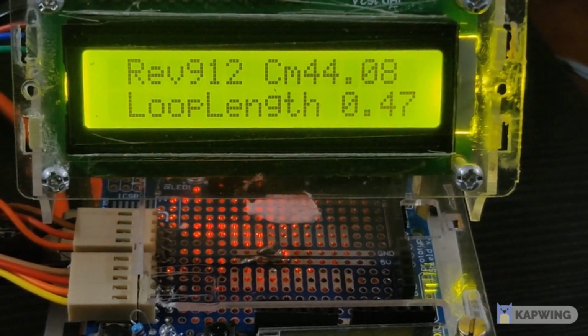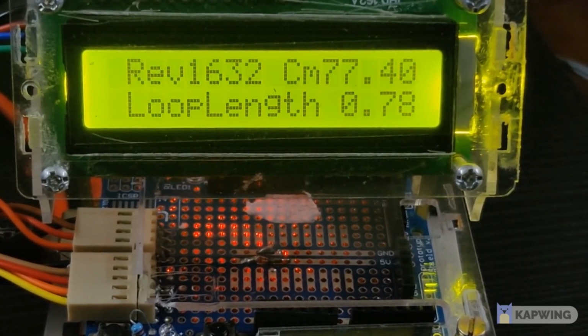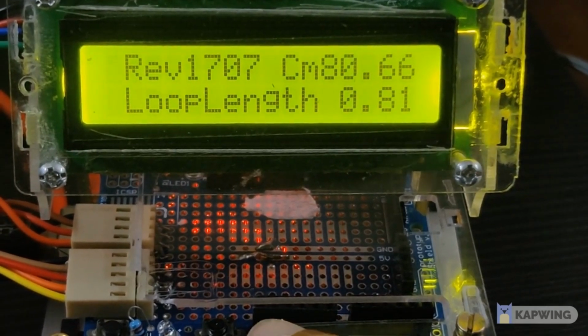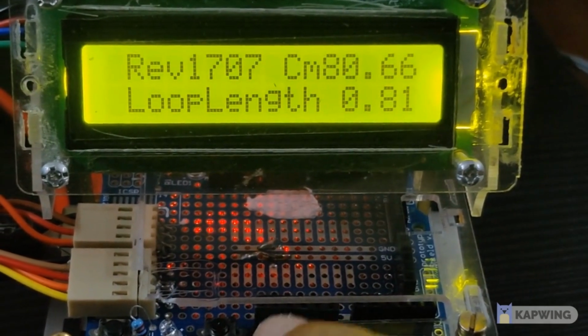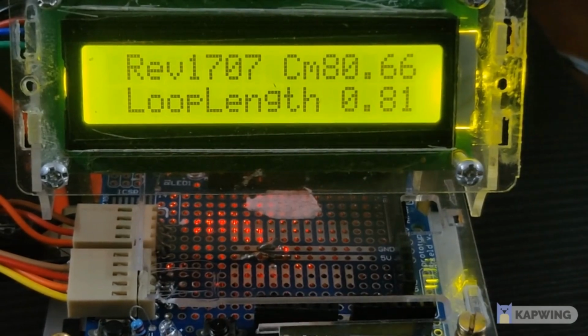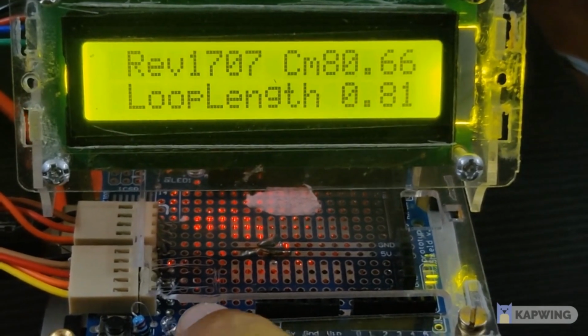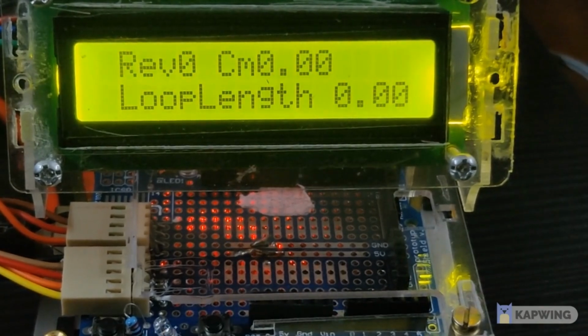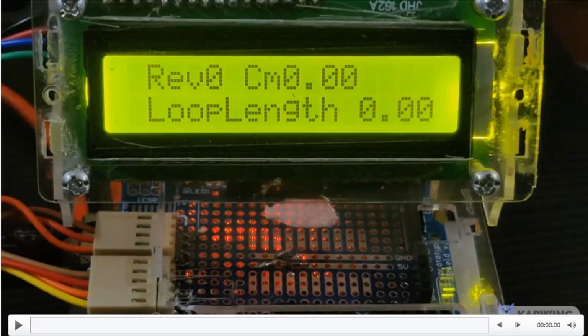When the carriage stops at the right side of the knitted panel, the rotary measuring device will also stop, and we will have a reading on the display unit. We note down this reading and press the reset button on the computer controller. The reset button will set the values of the rotary measuring device back to 0.